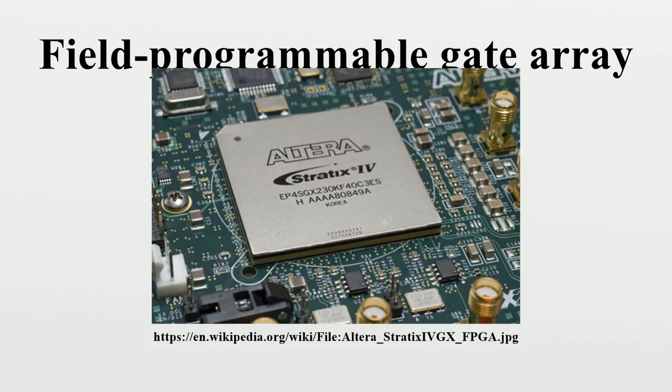The Microsemi SmartFusion devices incorporate an ARM Cortex-M3 hard processor core and analog peripherals such as a multi-channel ADC and DACs to their flash-based FPGA fabric. In 2010, Xilinx Inc. introduced the first all-programmable system on a chip, branded Zynq-7000, that fused features of an ARM high-end microcontroller with the 28 nanometer FPGA fabric to make it easier for embedded designers to use.